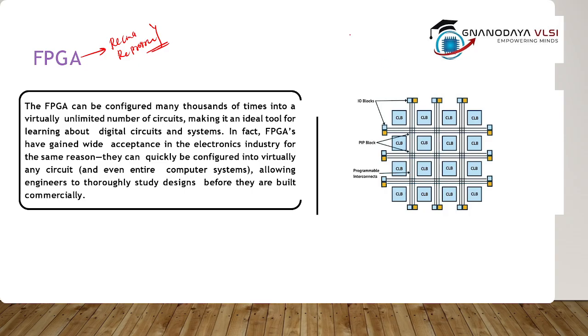Okay, in the CLBs you have some mux and one D flip flop, and lookup tables, LUTs, are also there. From the LUTs the output is given to the mux, and one more input is given through the D flip flop, and you are getting the output like that.